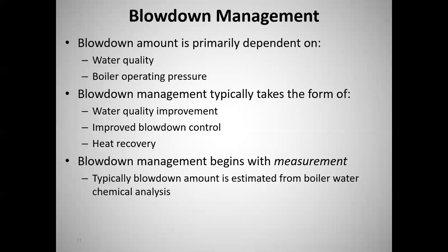Whoever sells you your boiler chemicals, the water treatment, Nalco is one of the big ones. There's a number of good ones. Tech uses, is it Nashville water treatment or something? And they're apparently quite good. Andy Loftus, the campus engineer, is quite happy with his water treatment people. Those people know the bleed rates, like in the makeup water and all that stuff, because they know how much chemical they're selling. And so there's a definite relationship. The more makeup water you bring into the system, the more chemicals you have to use. So over the course of a week or something like that, they can tell you very accurately what your makeup water rate is. Good place to go to get information.